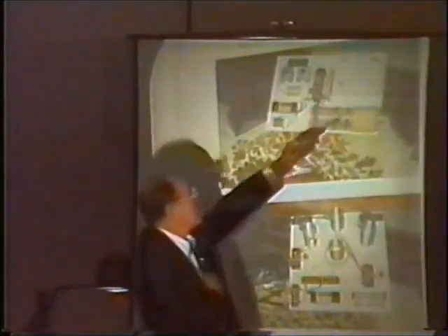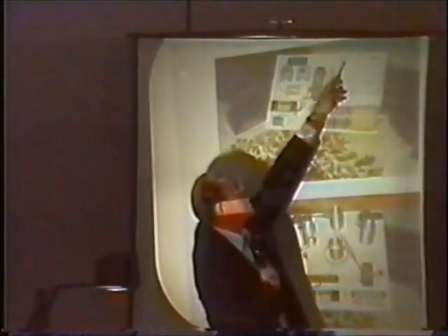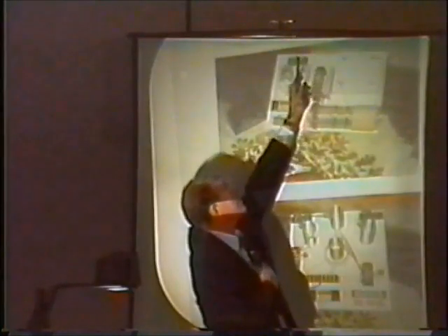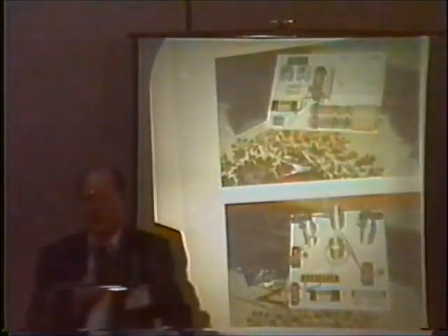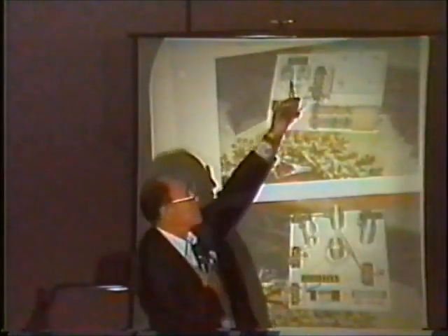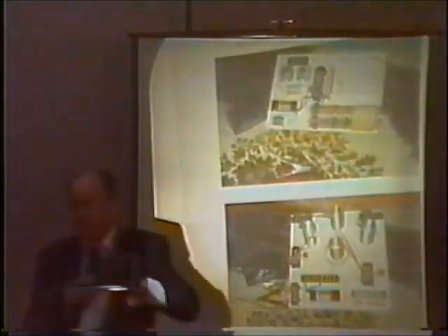Now, from your plus DC, you come over to the center deal here where the jumper is, and that enters into this inverter circuit, which is the device that you see here. It's what you get down at Radio Shack that you plug into your 12-volt outlet for running things from your automobile. It's 60 cycles at 120 volts.